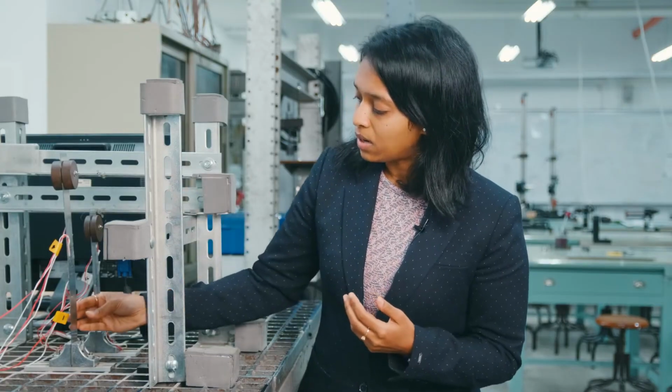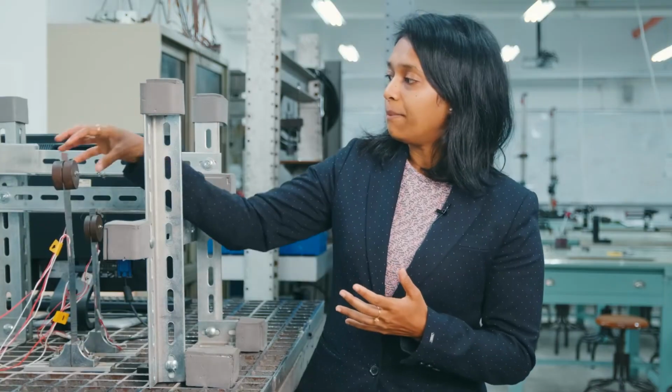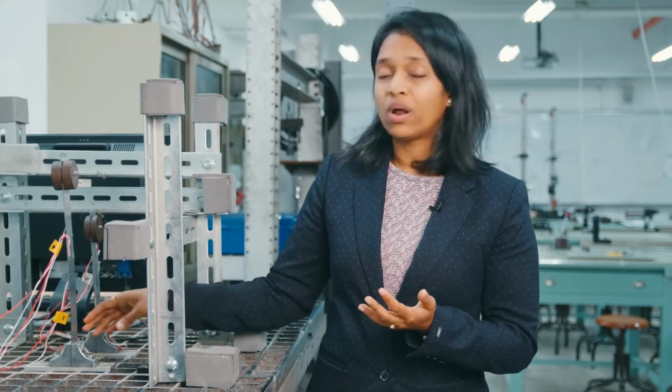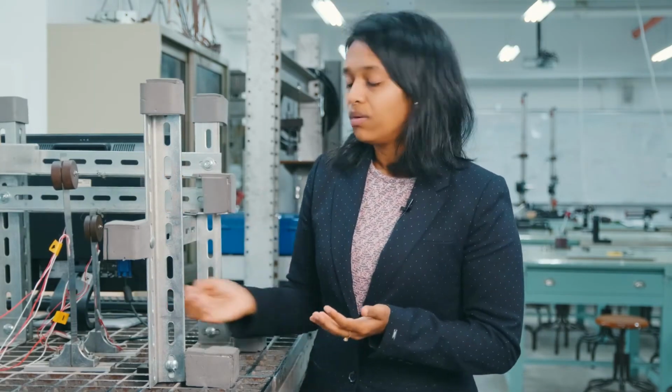What you see here is the setup we are going to use to do so. This is a plate which is fixed at the base, and there is a mass added to the top. This plate can be idealized as a cantilever beam which is fixed at one end and free at the other end. To derive the stiffness, we can calculate that stiffness as 3 times modulus of elasticity times the moment of inertia divided by the span cubed.